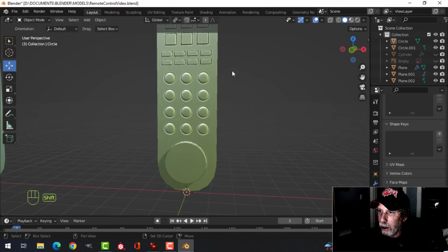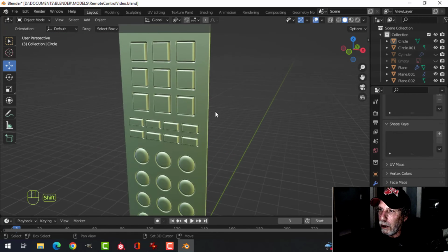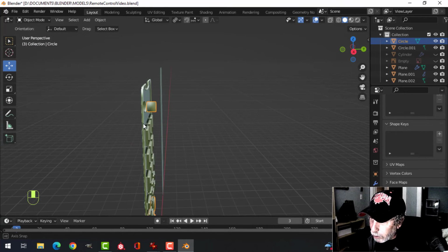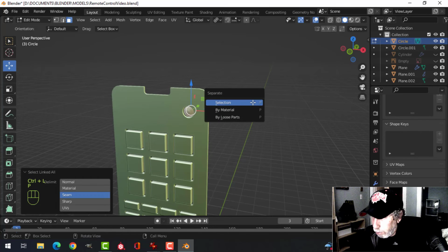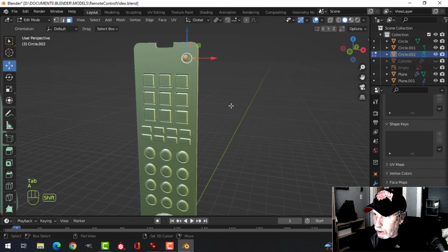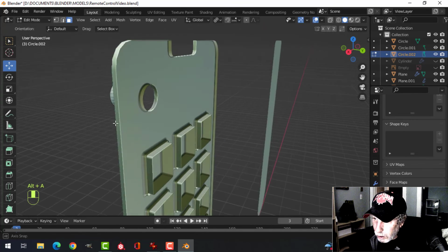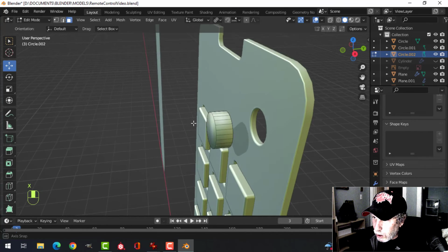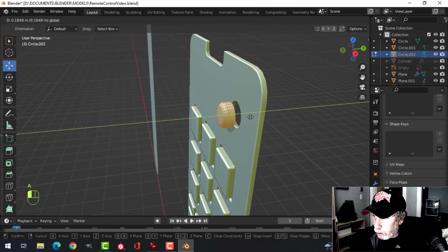I think I'm going to leave those like that. Yep. Okay. Oh, I did this one at the same time because it was joined. I'm going to do some work on this one separately, actually. I'm going to go into edit mode and select a bit and Control L and then P and break it out. This little straggler here got adjusted when I did those, and I forgot about him. Sorry about that. I'm just going to pull you through here and grab your rear there and X faces, and we'll bevel you a bit and pull you back in.